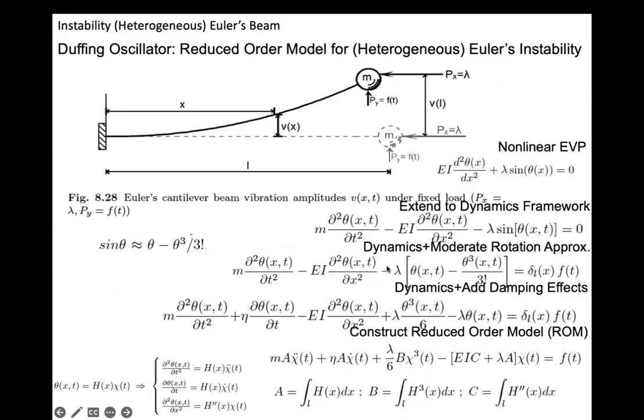Now you can also take a reduced modeling, and especially for non-conservative loading, which is the thesis of Rosa Della, basically you cannot reduce to the static, you have to go for dynamics. What you're then considering is basically the vibration when you have something at the critical load, you put it there and you give it a little push, like a small impulse, and you see how the vibrations are changing.